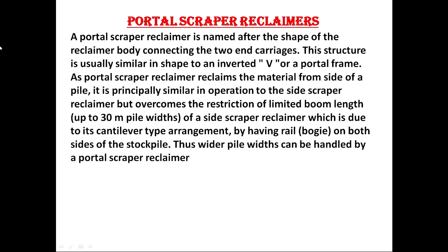Portal scraper reclaimers. A portal scraper reclaimer is named after the shape of the reclaimer body connecting the two end carriages. This structure is usually similar in shape to an inverted V or a portal frame. As a portal scraper reclaimer reclaims the material from the side of a pile, it is principally similar in operation to the side scraper reclaimer, but overcomes the restriction of limited boom length